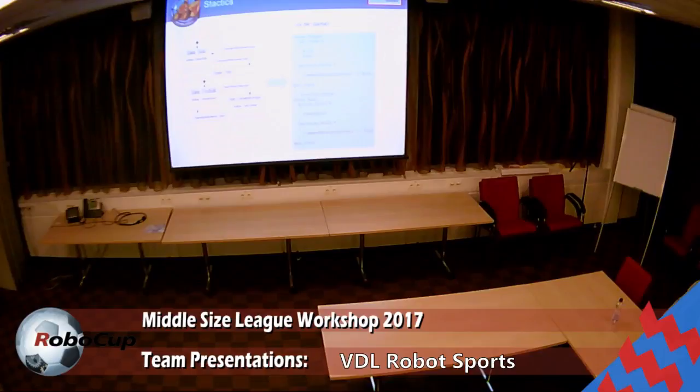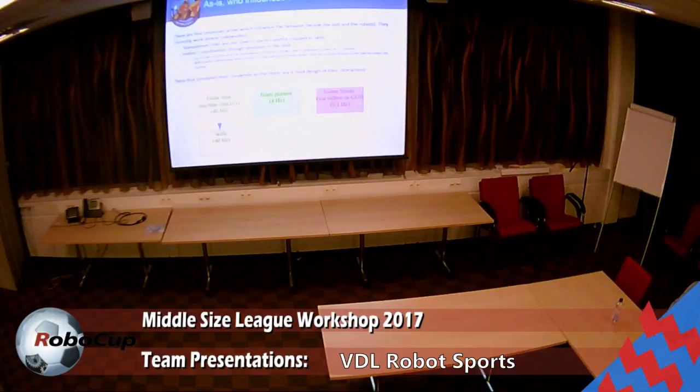We have implemented that in a programmable state machine. So we have skills, and we have decision skills. A skill is an action, and a decision is some sort of sensor reading. We can combine that in a script, and that script describes the behavior. Depending on the situation, we can change scripts, and the script is equivalent to the role of a player. So that kind of system we have.